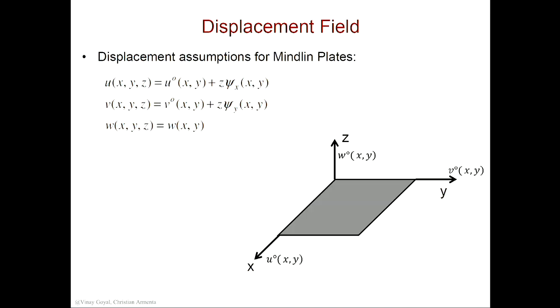This one right here represents the mid-surface deformations. And so you can see here at the top of the plate, say the thickness is h. The mid-surface is right in the middle. Then what is z at the top of the plate? H half, right? H half.